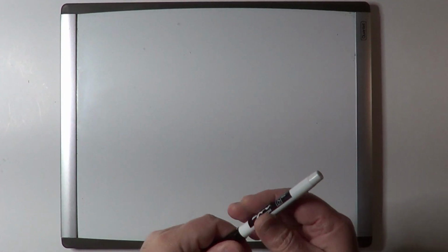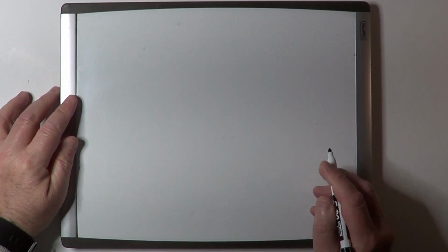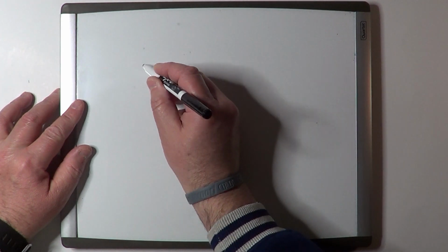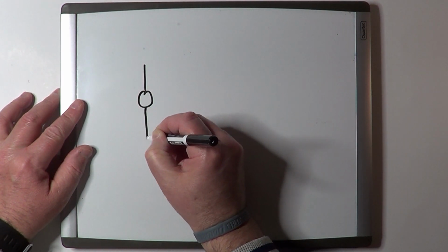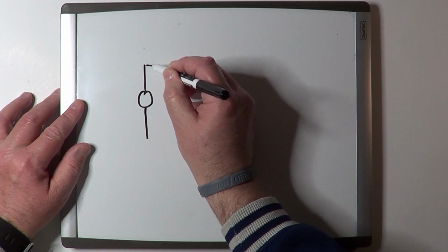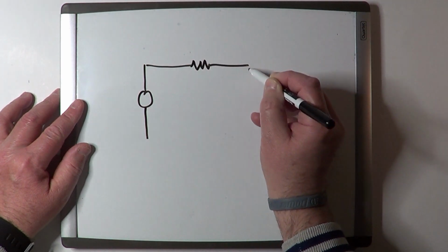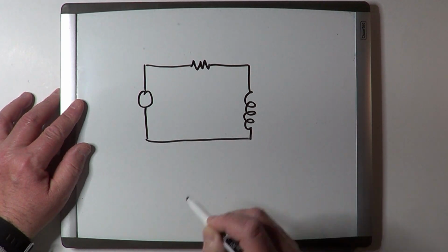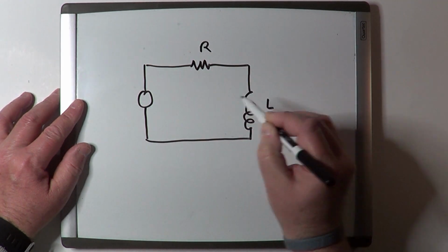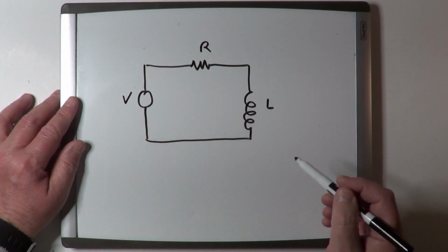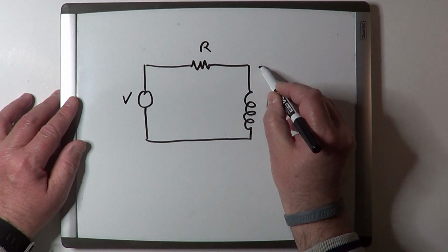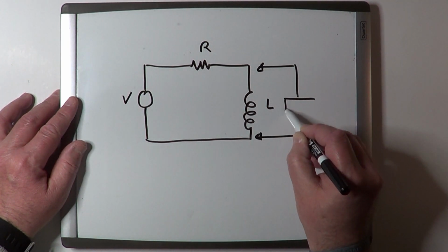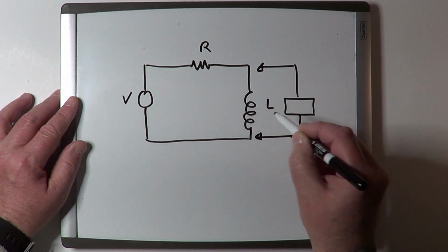Let's start with a simple circuit to measure the back EMF generated by the inductor when we change the voltage powering the circuit. The circuit will have the generator over here, in series with a resistor and an inductor. The oscilloscope will be connected directly to the leads of the inductor, so right in this point and this one, so we can measure directly the voltage at the inductor.